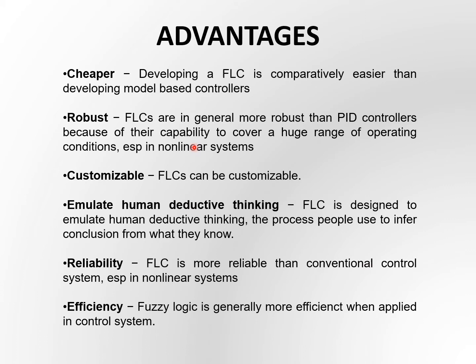Okay, the advantage of fuzzy logic is that it is comparatively easier than developing the model base where you have to get models and all that. It's robust in general, more robust than PID because of the capability to cover a huge range of operating conditions in the knowledge system, as we mentioned before. It can be customized to different areas and different systems.